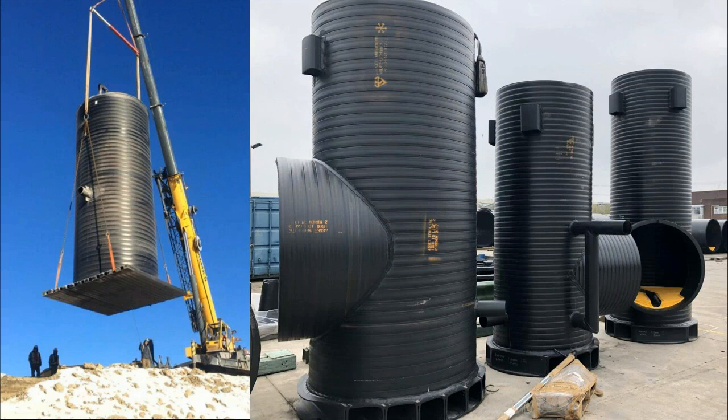similar to pump stations. We can also produce pump stations with all the internal components, piping, fittings, breakaway fittings, guide rails, all pre-manufactured and installed and ready to be backfilled and plumbed in the field. This significantly reduces the installation time of these structures. It also provides a level of quality control, given that we can test the system and make sure it's leak-free prior to it leaving our production facility, which we'll talk about here in a second.